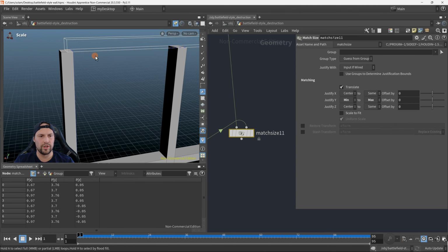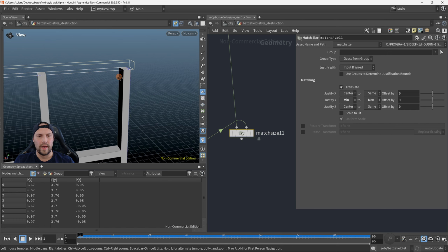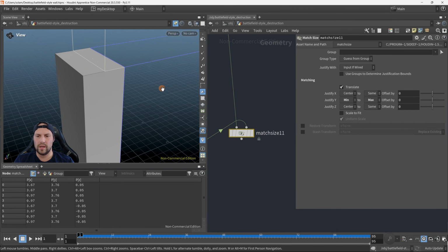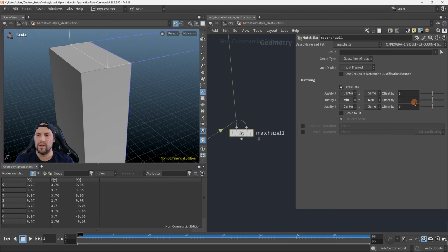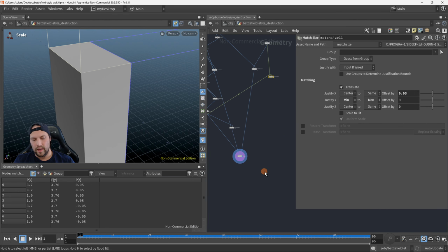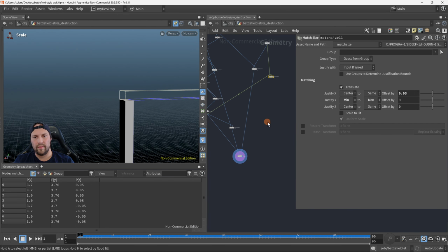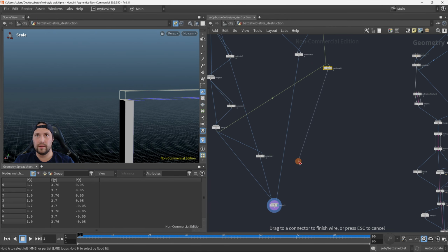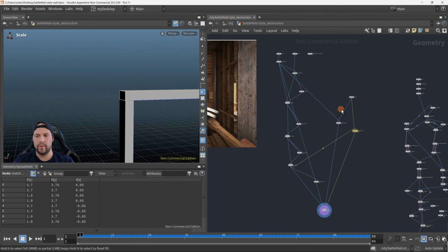It's really not flush to this part right here, and it sticks out a little bit there. What we can do in this kind of scenario is there's an offset by slider that we can try to use. It's going to be, I think, X direction, yep, to try to reel it back a little bit like so. And if we do that and display everything like this, let's not forget to take this little pin and put it inside the merge. So that's what we have created, okay?